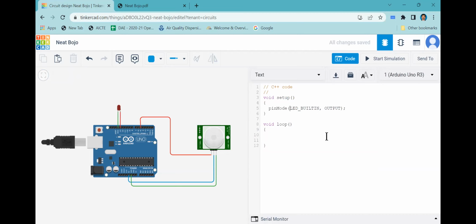Here we should understand which is the input signal and which is the output signal. The PIR sensor is sensing something, and a signal is sent to the Arduino as an input. That is number one. So I say this is 5, because I have connected it to digital pin 5. I say this is INPUT. Be careful here with case sensitivity, it should be capital letters.